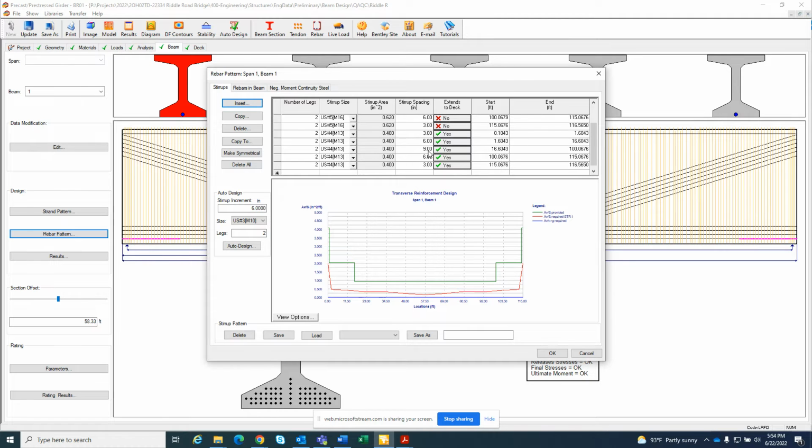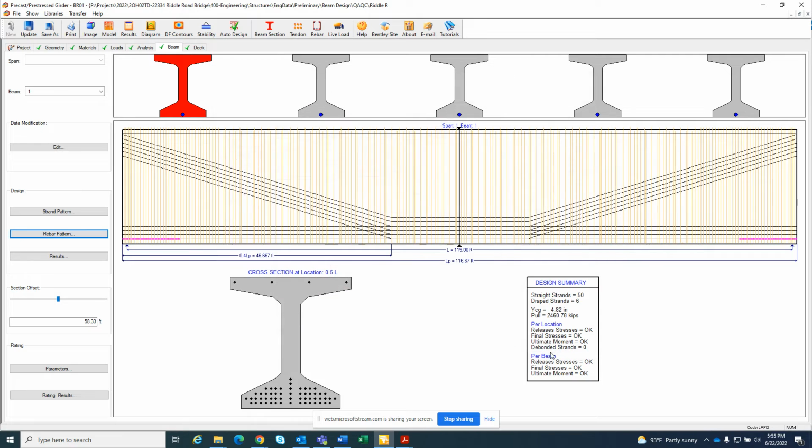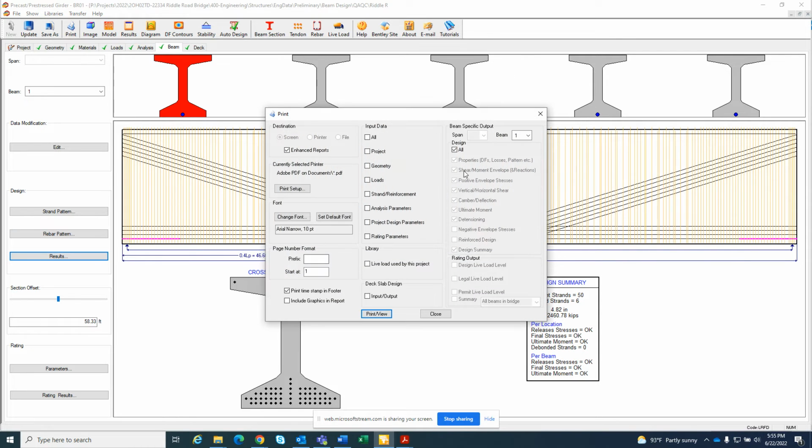So let's say you want to make it 12 inches here, 15 inches. I'm trying to match the spacing with the welded wire reinforcement D31 and D20. If it is 3 inches here, 3 inches, it's matching. So it's 6 inches, 6 inches here. But I want to see by changing this to 15 inches rather than the 12 inches we have here. Okay. You do that, go to the results, save view.